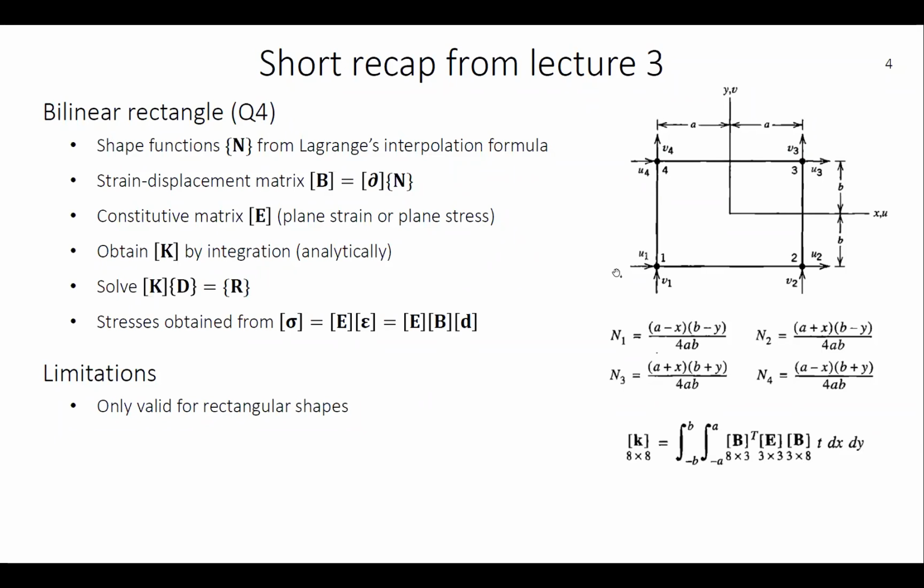That is also part of exercise A, that you will evaluate one component of this stiffness matrix. Doing the full 8x8 is a little bit time consuming if you do it manually. If you try to evaluate this integral in, say, MathCAD or some program, it's likely to crash because it's a little bit time consuming. As a hint, you can actually do it using the symbolic toolbox in MATLAB to evaluate this whole matrix directly. But you are supposed to do it manually by hand just to get the feeling of it.